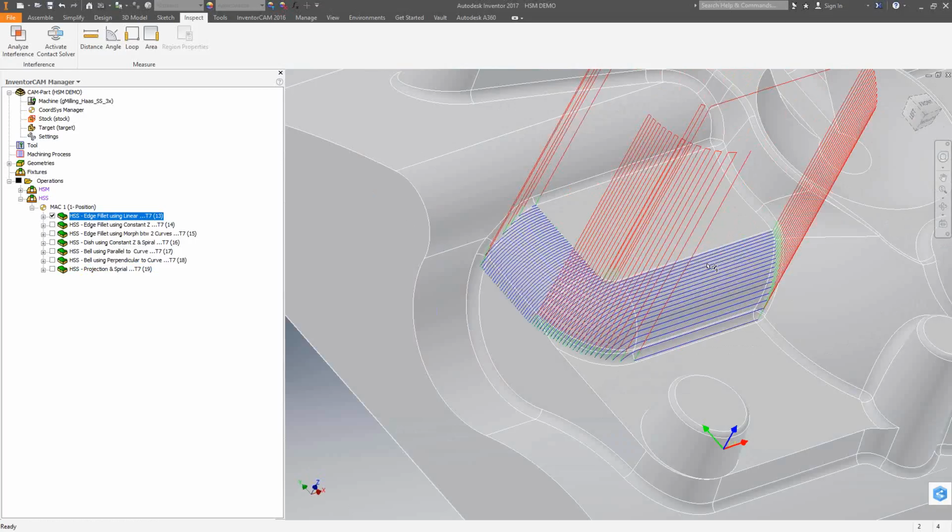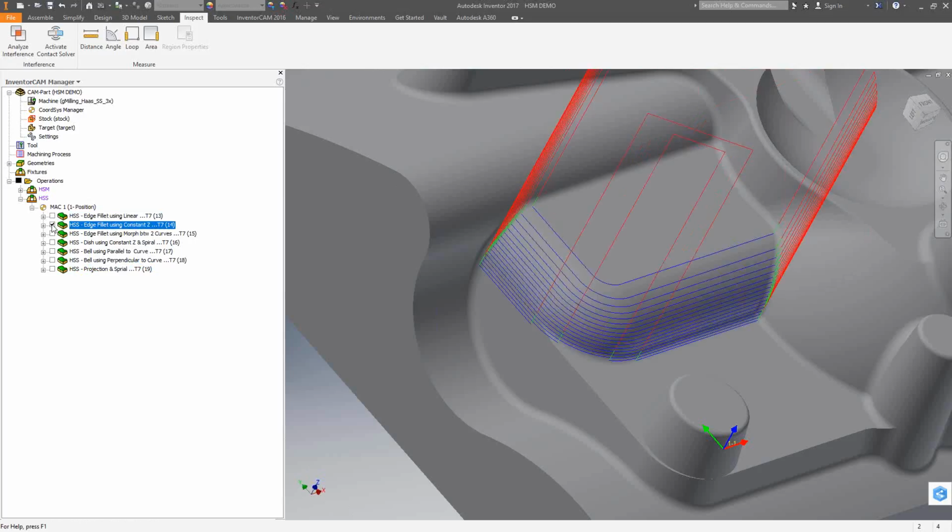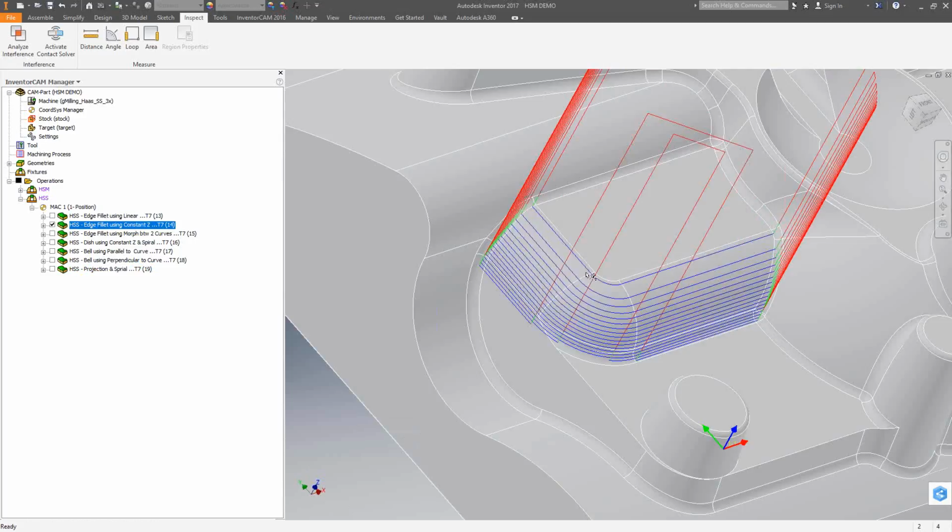of the movements. With a linear HSS toolpath, we're just going parallel to the x-axis or whichever line I choose, and we're trying to approximate that surface using that. In a general sense, it's okay, but it's not exactly giving us the exact finish we're looking for. If I switch this to constant Z, it's the same sort of thing. Again, like we've seen in video 11, the step over is in the Z-axis, so we tend to get a little bit of fanning out as we go down this surface.